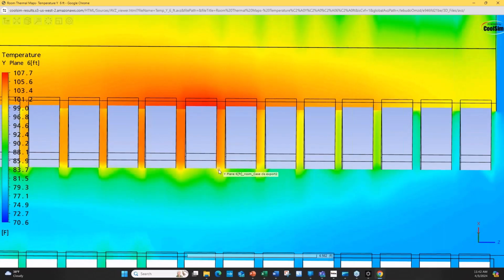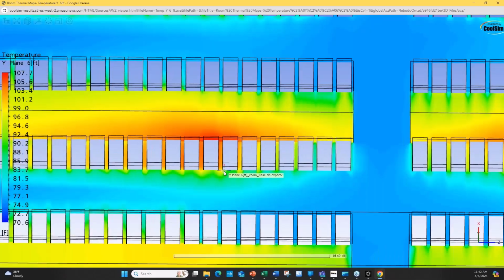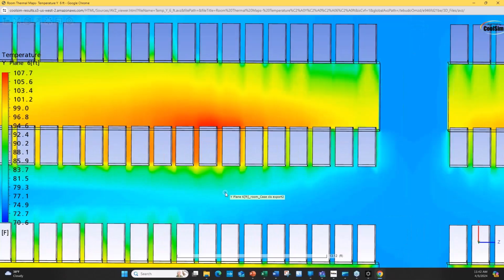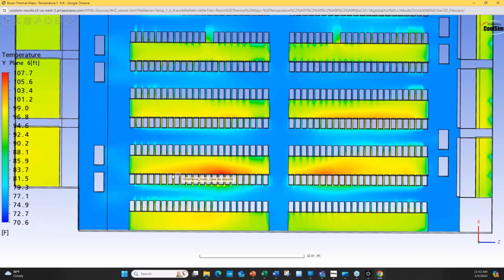So for those of you who are in colos or working for colos or doing this kind of work, it's really important to stress things like proper cable management, proper sealing around the rack, proper sealing under the rack, inside the rack. Make sure all the blanking panels are in place, because the integrity of the design assumes that you have proper sealing between the racks and the hot and cold.